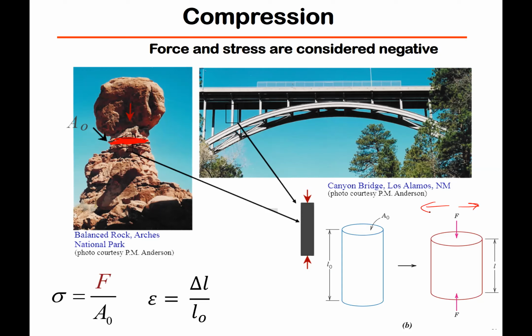And this applies for most materials where you squeeze it in one direction, it increases in another direction. Of course, there's always specialty cases where you could have foams with voids, where that might not be the case, because when you're compressing a material, let's say a foam with a lot of voids, it wouldn't expand as much because the material is actually now occupying the voids that were there before. Okay. So while this is generally true, for the most cases, it's not always true, but of course, given that this is an intro class, we'll focus on the cases that are most common as opposed to all the exceptional cases.